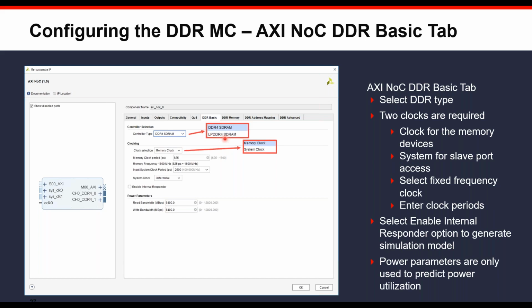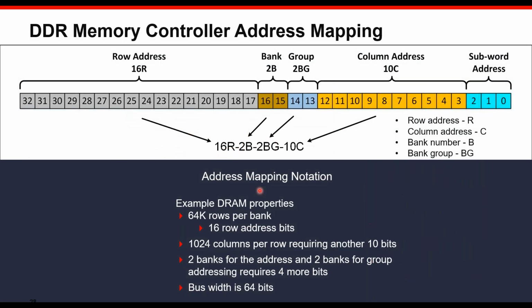The regular I/O is extremely capable of doing what we looked at 20 years ago as a high-speed serial I/O gigabit transceiver. Just the regular I/O inside of the Xilinx I/O banks can do better than what the first couple of generations were able to do. So you would open it up like anything else in the IP catalog, start defining your requirements for that memory controller, and then connect it up as you need, whether it be AXI across the NoC or other ways of doing that.